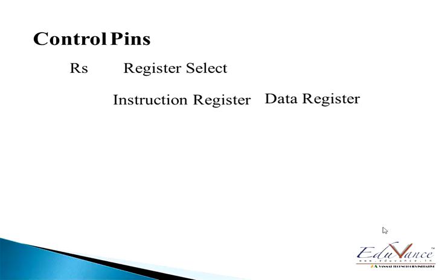Now, what is the function of the instruction register and the data register? The instruction register will determine, say, the position of the cursor, where you want to write, how you want to write. That is, the instructions given to the LCD are controlled by the instruction register. And what is the data register? The data register is where we will be sending the data which we want to display. Since it is a character LCD, every character which we send will be in ASCII format.